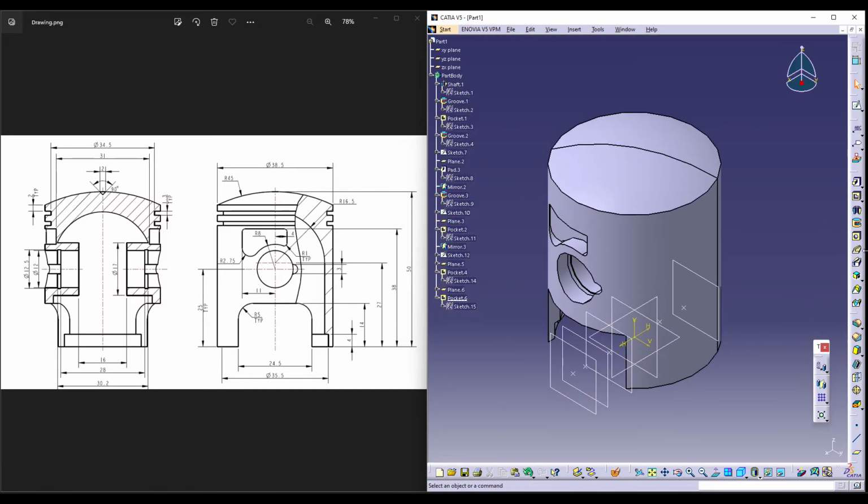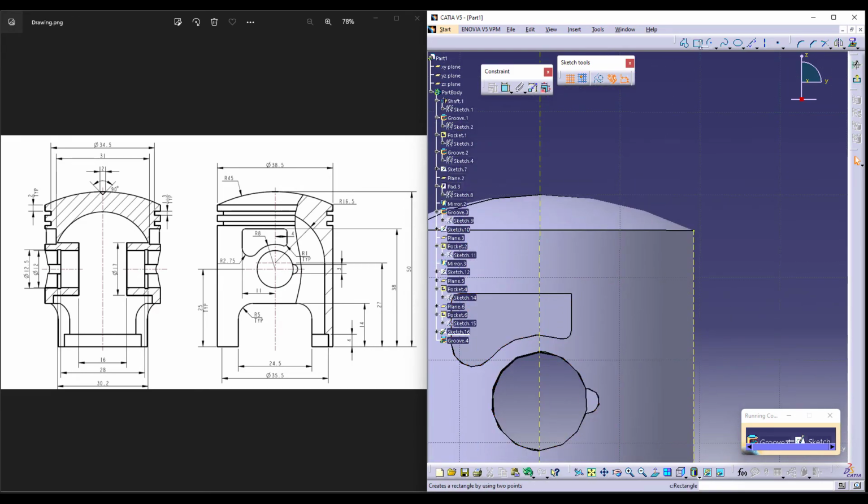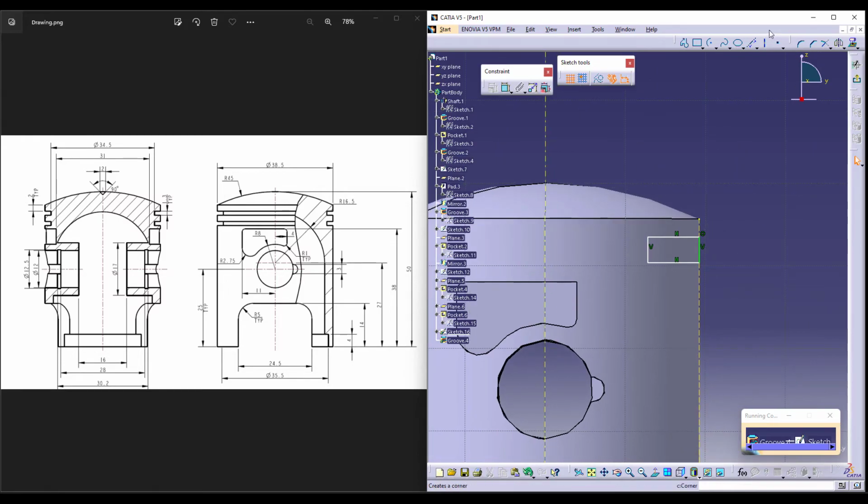We can make these slot cuts too using our groove command. Again, I'm taking the front plane, selecting the previous axis only, and then I'll be selecting the cylindrical body because we require the cylindrical body reference. Now, beginning, it starts at a distance of 2. So let me try to take it at a distance of 2 from the edge face, as in from this face. From this edge to this edge is supposed to be 2, and the groove is actually only 1.3. This is only 1.3.